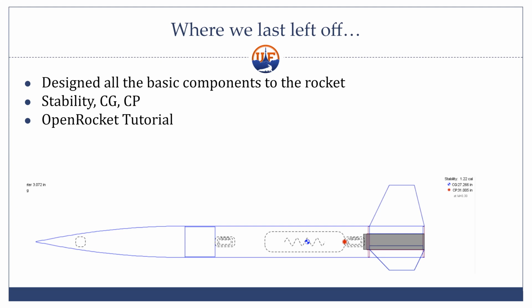The other additional thing is, if you want to actually get your rocket back down, you're going to need a parachute. That will deploy at apogee, the tallest part of the flight, and we choose that point because it's where the vertical velocity is 0. So it's the slowest point in the rocket's flight, which makes it the least force-intrusive part of the flight for your rocket. That's really important because when the parachute deploys, it's going to tug on the entire system and potentially break it.